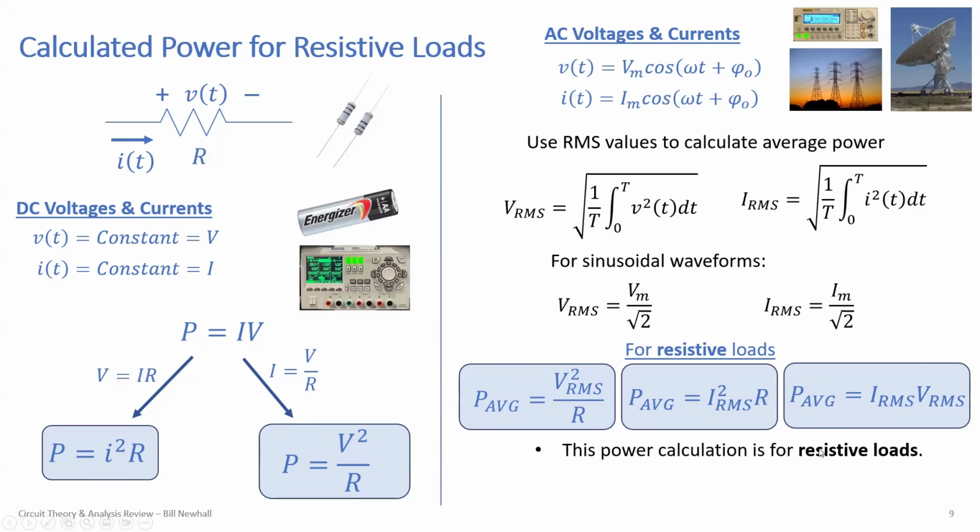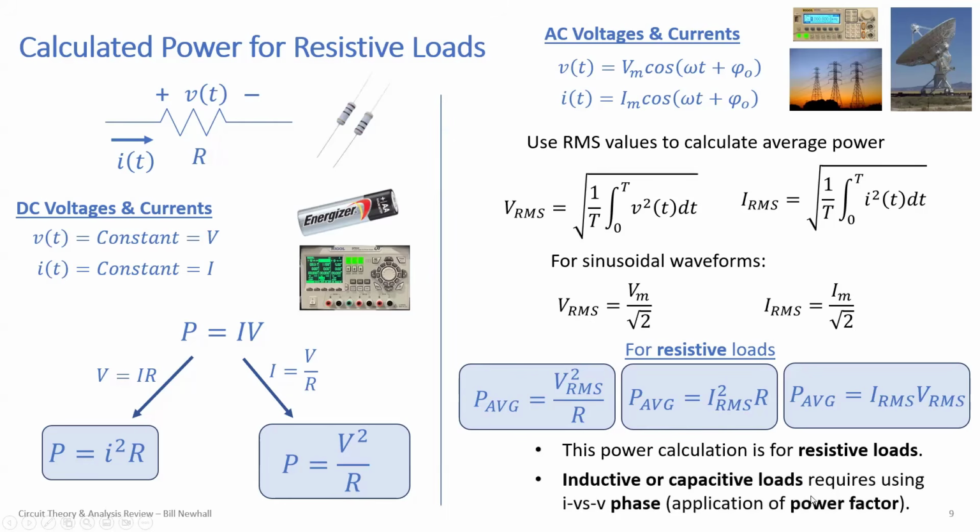So this power calculation, again, I warn it's for resistive loads, because if you have inductive or capacitive loads, the voltage and current are not in phase. Okay, and so you can't use these equations for calculations for inductive or capacitive loads unless you apply a power factor. We're not going to get into that, but if you're dealing with AC power, you learn about power factor for capacitive and inductive loads.